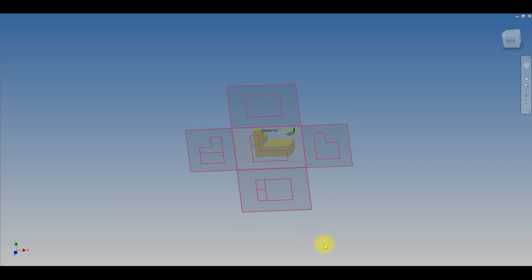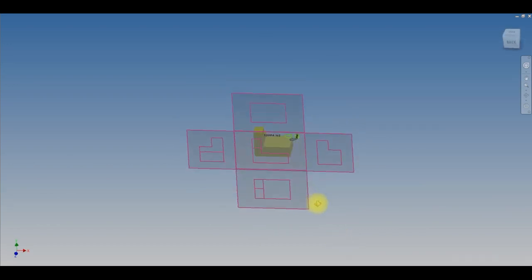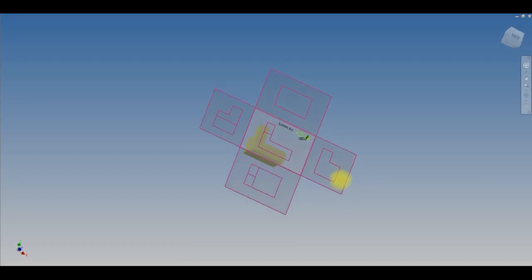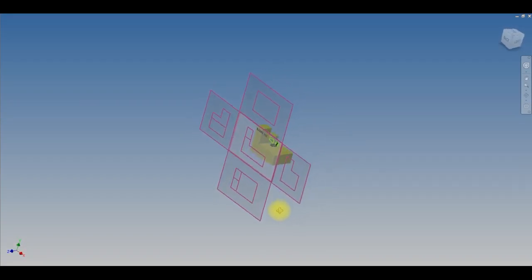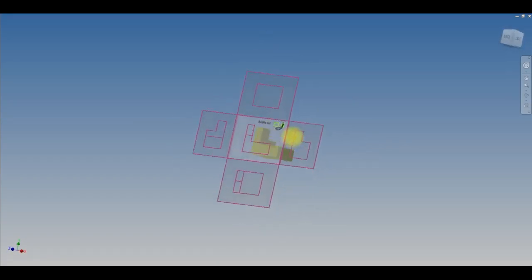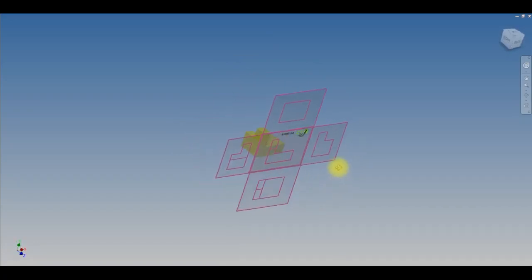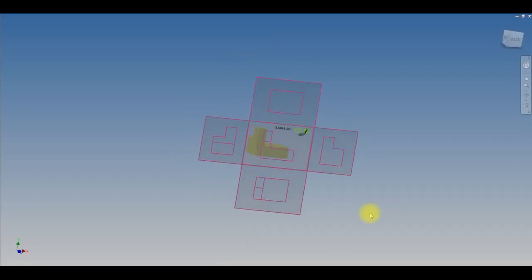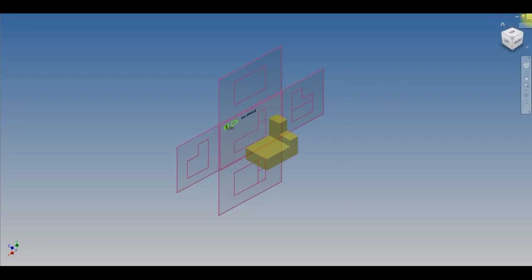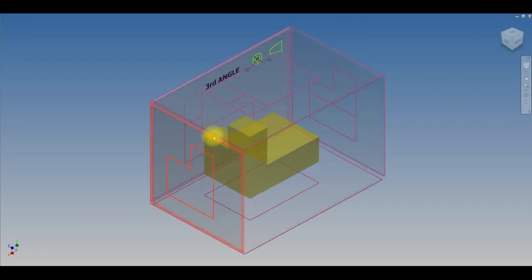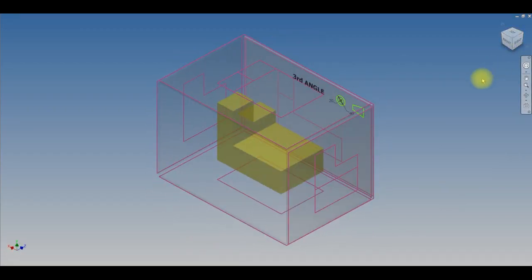But if they're not really switched on for some reason on that particular day, a mistake can be made, and the draftsman could be blamed for it, that it was drawn in the wrong projection for Australia. The Australian standard for drawing is that it's all done in third angle projection. I don't need to show you much more about this so that you don't get confused, but it's important that everything is done in third angle projection.